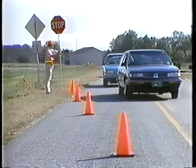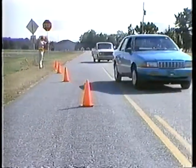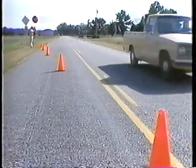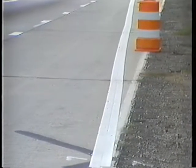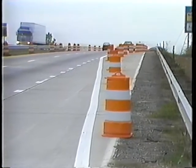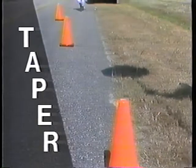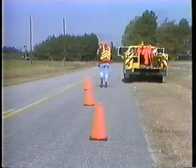The transition area should be obvious to drivers. The correct path should be clearly marked with channelizing devices so that drivers will not make a mistake and follow the old path. If the existing pavement markings create confusion, interim markings should be used. A taper is a series of channelizing devices placed at an angle to move traffic out of its normal path.